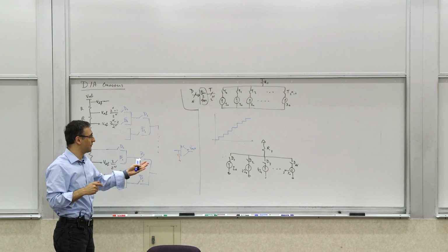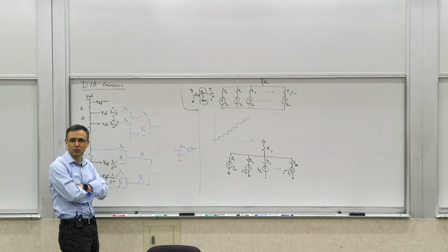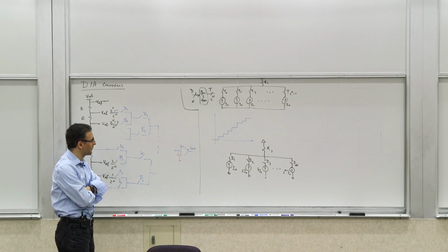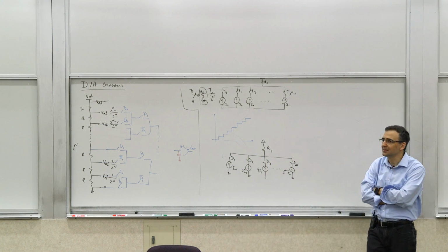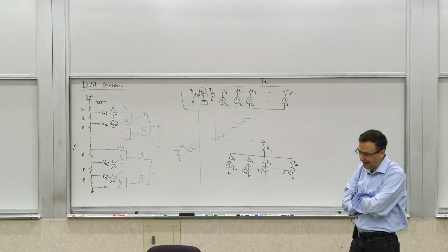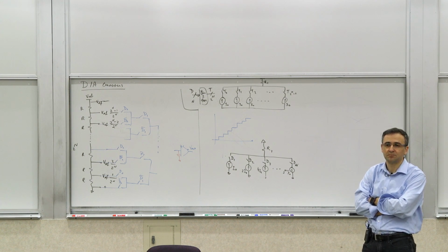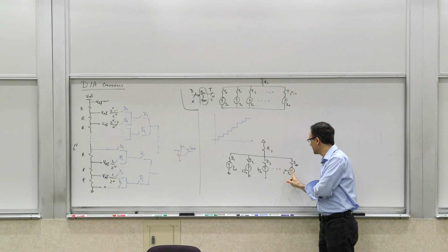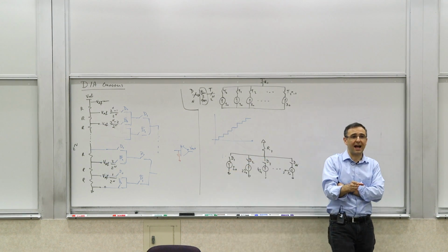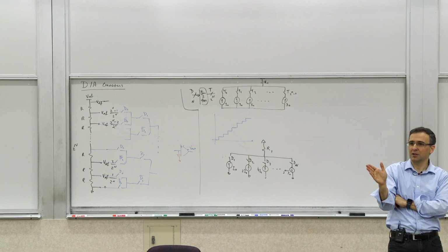So now we've reduced it. If we had, for example, a 12-bit DAC or 10-bit DAC, we've reduced it to 10 devices as opposed to 1,000, or 4,000 in the case of a 12-bit. So that sounds like a good thing, right? It's much more compact. But do you see any disadvantage to this? Can you think of a disadvantage? Yes? In the manufacturing process, now you have to be able to make 2 current sources that are 1,000 times different. This current source is 1,000 times larger than that. Not only that, but it also has to be accurate to the precision of that smallest one.